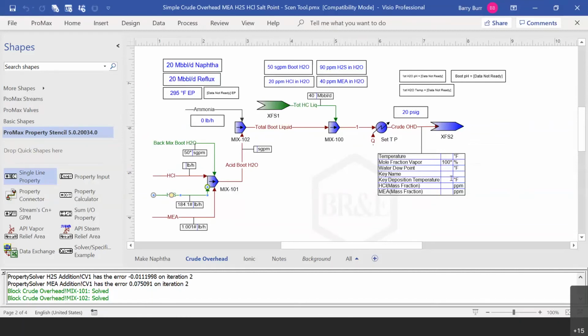Now, if you took the condensed hydrocarbon liquid and then further cooled it before feeding back to the stage, then I would see how you would have a chance for some non-equilibrium third phase. That's the way I see it anyway.